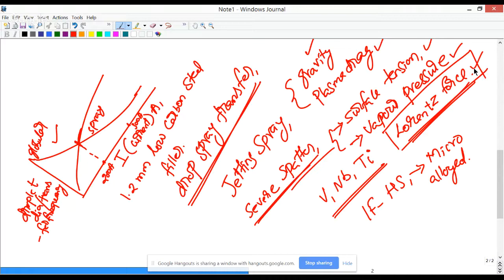So question 4 on assignment 1. The enhanced ductility of dual phase steel is primarily due to the formation of mobile dislocations at the interface. So when you do a TRIP steel heat treatment, as I already explained, you form martensite amidst the ferrite matrix. There is a volume accommodation leading to formation of mobile dislocations at the interface. That gives the improved ductility.